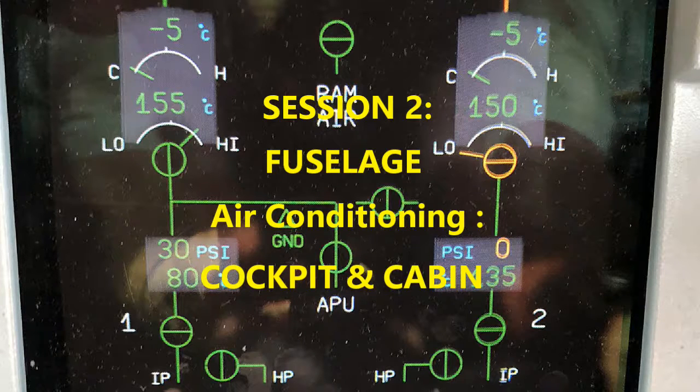So for example, let's say that in the cockpit you select pack 1 to be off. Then the flap changes position, and it's going to connect the supply duct to the pack 2 mixer chamber. So it allows one way or the other, it's going to get that air. The function is just making sure that there's a good flow separation between the 2 packs, and that there's just fresh air quantity going on there when one of them is off.